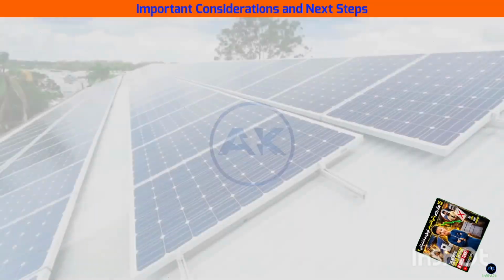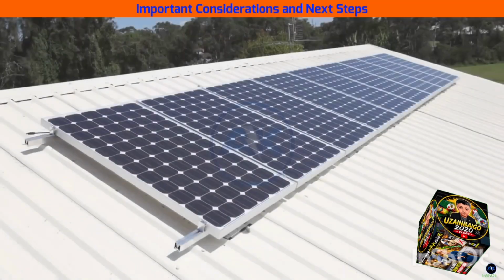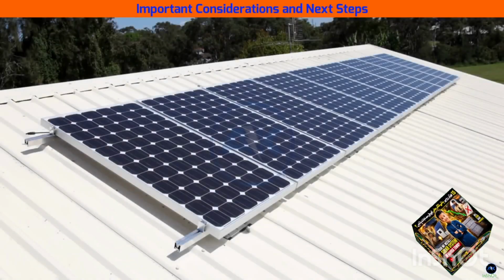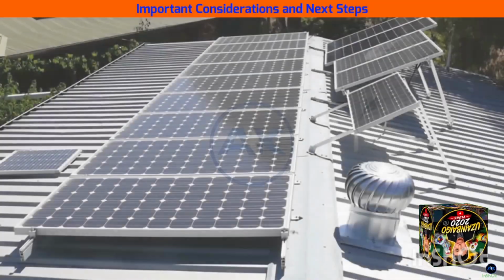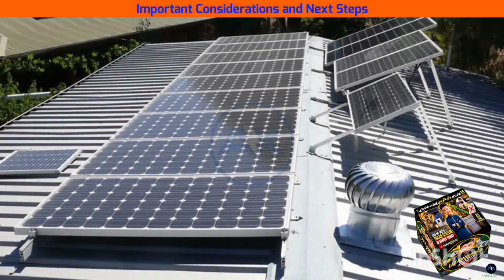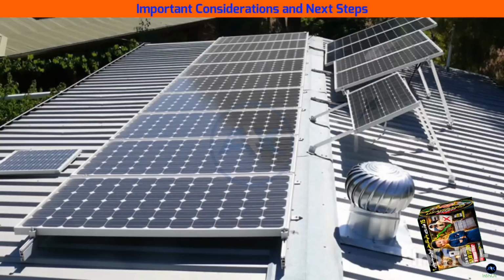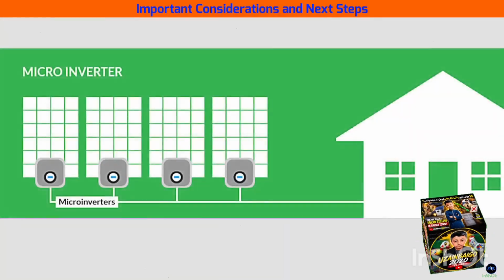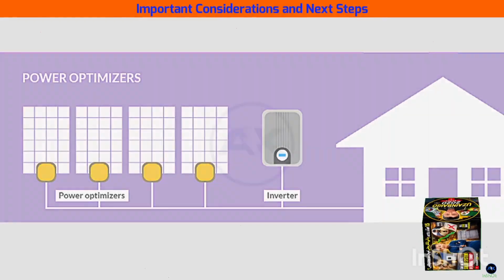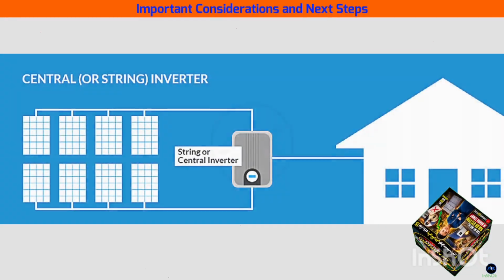Roof layout: this calculation assumes you can physically fit 2 strings of 7 panels on your roof without significant shading issues. Real-world roof layout often dictates string lengths. Shading: if a string experiences partial shading, it can drastically reduce its output. For roofs with complex shading patterns, you might consider micro-inverters or optimizers instead of string inverters, or design shorter strings to minimize shading impact.